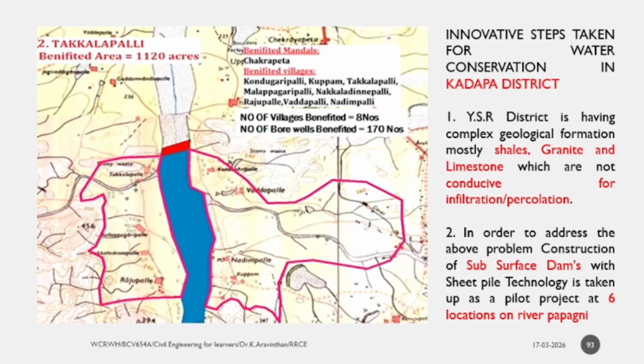You can see, sir, where I can construct this kind of dike is where my place consists of granite. Granite is a hard rock, no? If you are living in such a place, naturally the groundwater will not infiltrate. A granite rock will not allow infiltration. If you have sand and you pour water, will it infiltrate quickly? Yes, sand infiltrates quickly, no? So if you have a granite place, it will not infiltrate. In those kinds of areas, you can construct this.